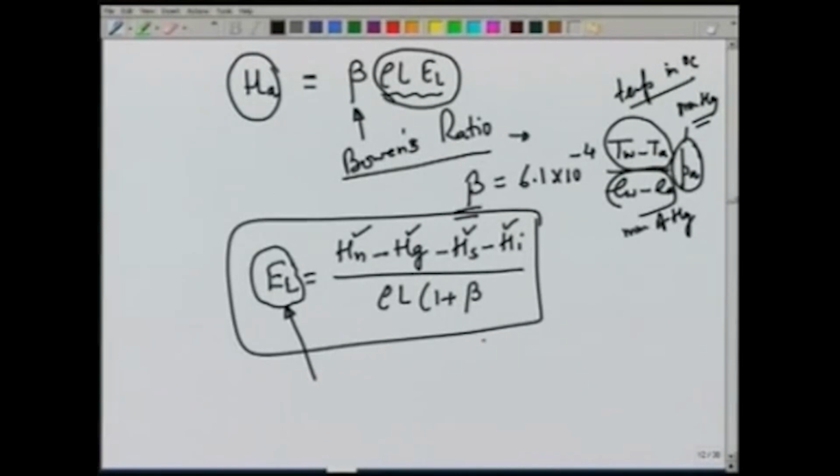So, we have seen three different methods: one measurement using a pan, one based on some empirical equations derived for some local conditions, but empirical equations we may be able to derive for our own area of interest also. And then the theoretical equations which are based on water balance or energy balance, they will need measurement of certain quantities, but these quantities are not very difficult to measure. So, we can use one of these equations to find out the evaporation.